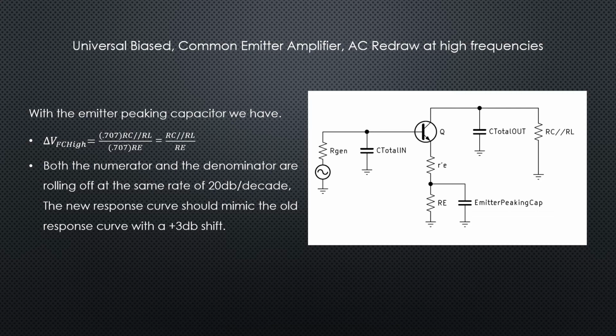But this should extend out our bandwidth, and certainly at our current high frequency cutoff, it'll bump us back up 3 dB. As you can see, the 0.707s cancel and it returns us back to our 0 dB point with our original voltage gain.